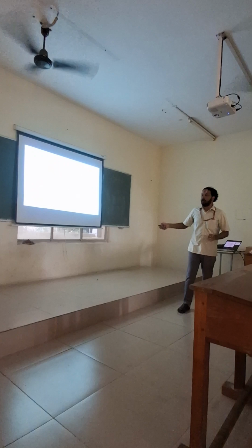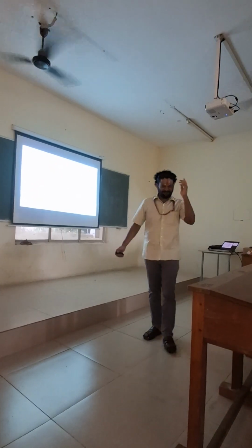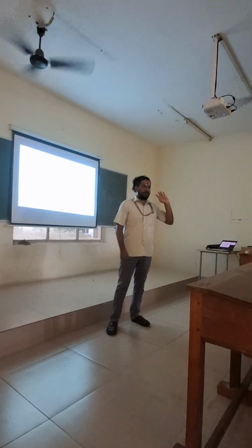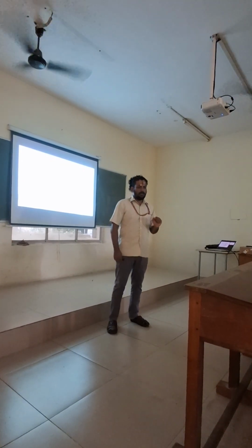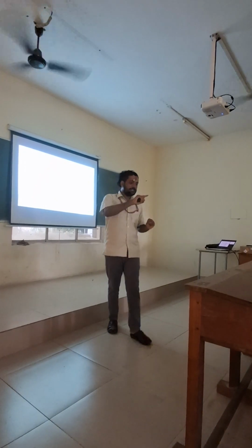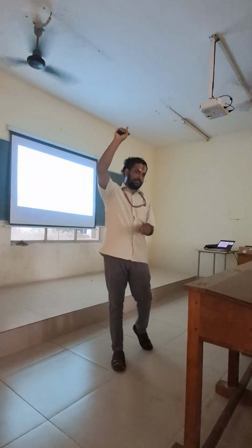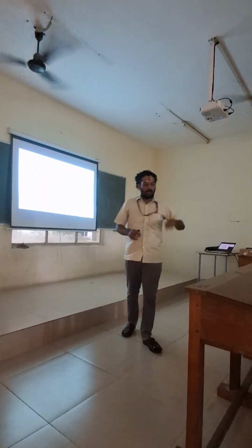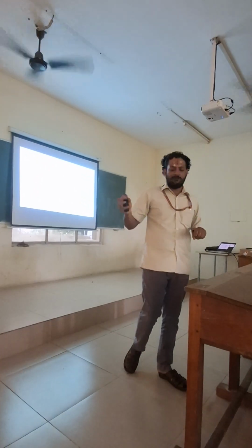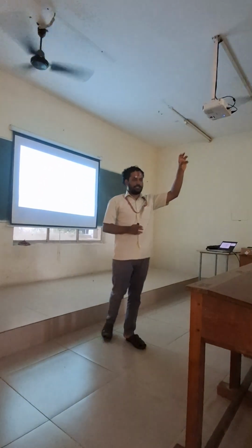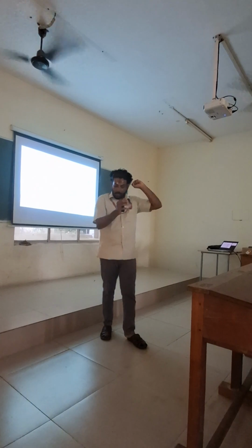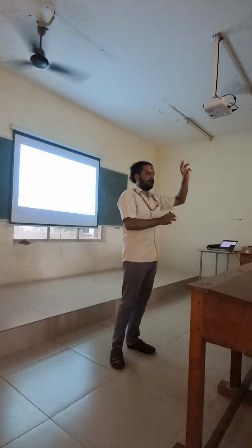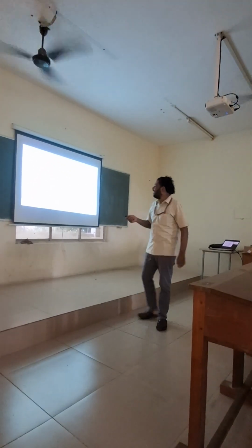Then we have what is called the Auger model, where three particles are interacting. So an electron recombines with a hole and pushes an electron in the conduction band upwards, taking the energy. Or a hole absorbs certain energy from a different particle, gets excited, and then the rest of the energy is transferred from a different particle, which pushes it down the valence band. So we have three different types.